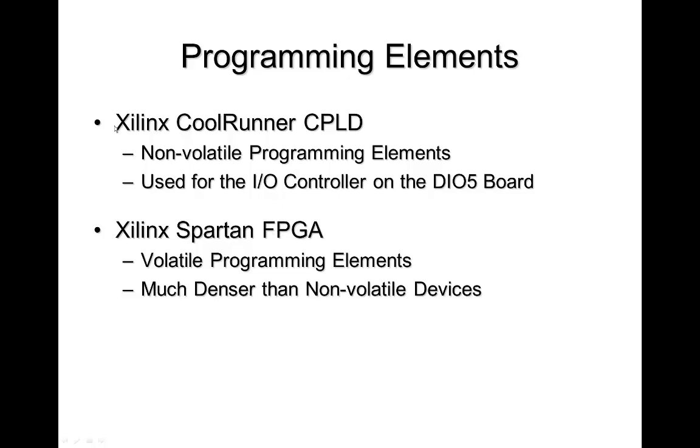Okay, so I guess we're at the Xilinx house here, and we'll talk about CPLDs versus FPGAs. In general, CPLDs oftentimes use non-volatile programming elements, but some do use volatile. Then we have the Spartan FPGAs, which use volatile programming elements, and usually FPGAs have more logic on them.